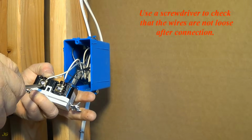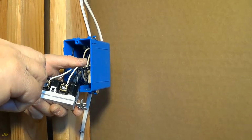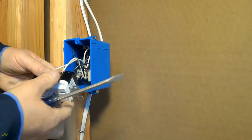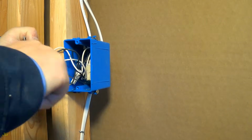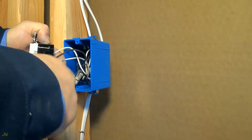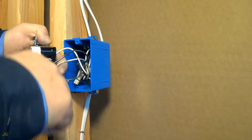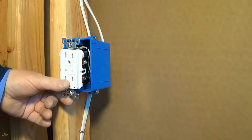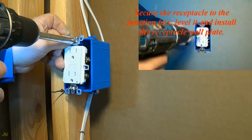Use a screwdriver to check that the wires are not loose after connection. Secure the receptacle to the junction box, level it and install the receptacle wall plate.